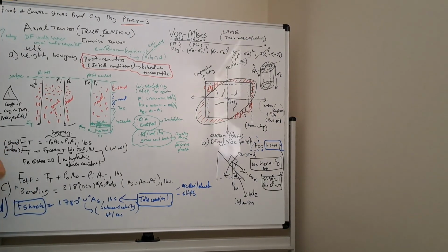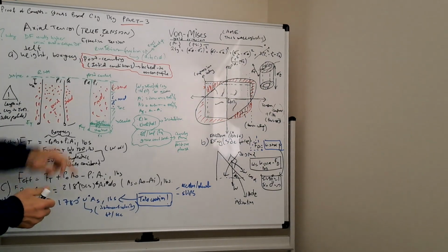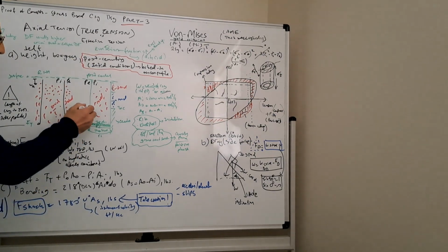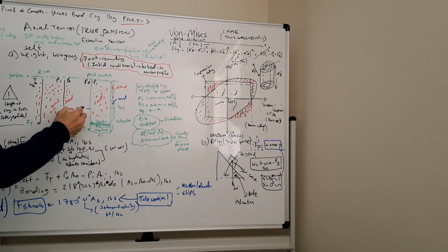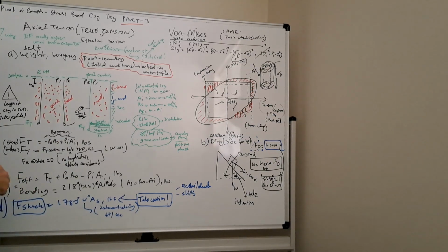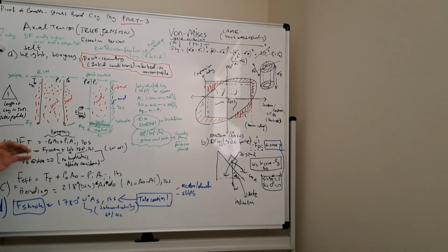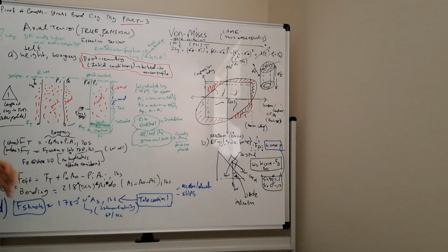And then below, let's look at the true tension value at the shoe. So what will be the difference between true versus effective tension? If I put a kind of gauge over here, a strain gauge, to measure the load felt at that point, then that will be the true tension, right? However, if I want to look at a buckling concept, where I need to look at just effective tension, then I will use the effective tension.